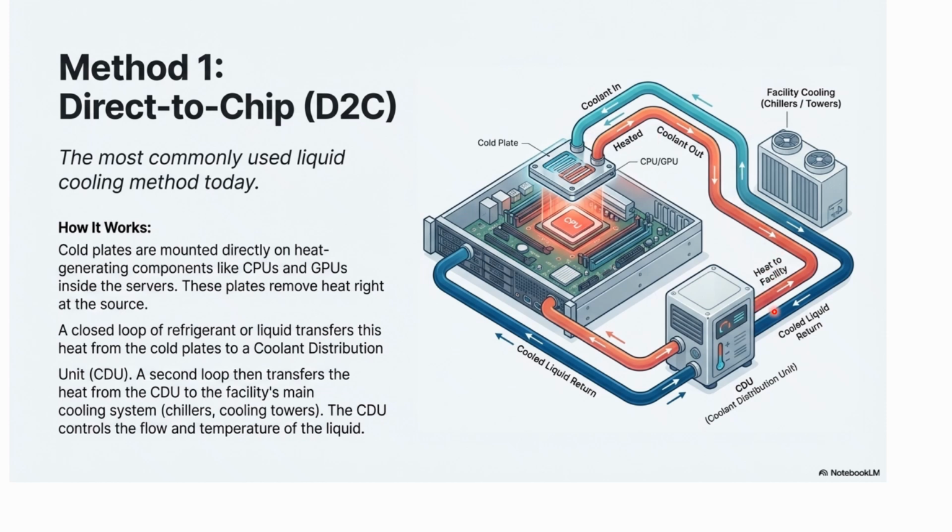It runs between the CDU and the cold plates on those very sensitive, very expensive chips. And that's using a specialized fluid. High quality, super clean fluid. Then the second loop connects the CDU out to the building's main cooling system, the cooling towers, the chillers. The facility water. Right. And the beauty of that is that the, let's say, less clean facility water never, ever touches your high-value IT equipment. The CDU is just a heat exchanger between the two.